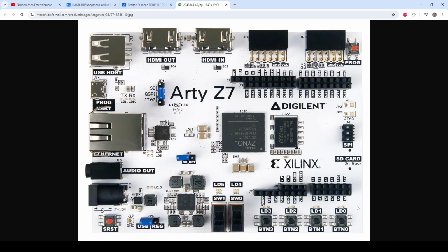For our specific case, and as is the case for many designs, we will be using, or we have been using, a MagJack connector which integrates the magnetics, which makes our PCB design and layout far simpler and a bit less stringent than if we were using external magnetics.